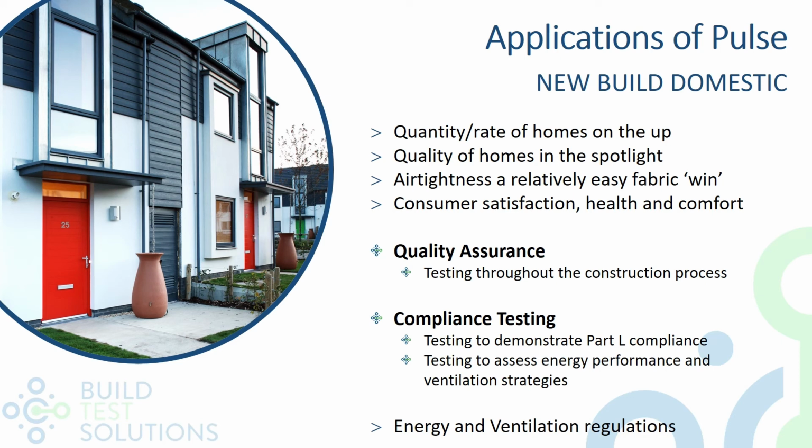I think it's fair to say there's a huge amount we really don't know about how our buildings behave under ambient conditions. We're all too familiar with testing at 50 pascals and then plugging those numbers into SAP using this divide by 20 formula to derive what that might mean at ambient or infiltration levels, and I think it's well understood that a single value correction factor is not all that accurate.